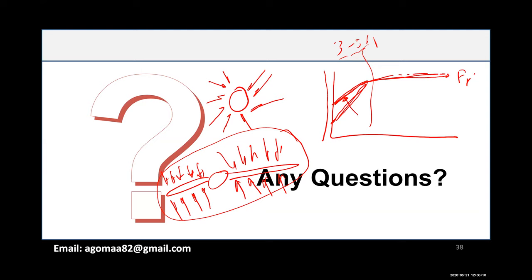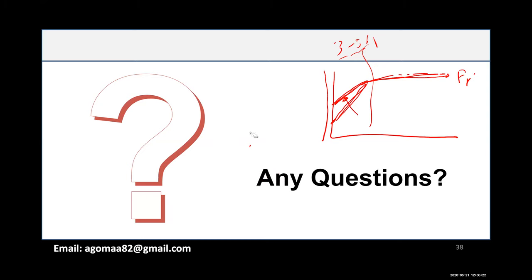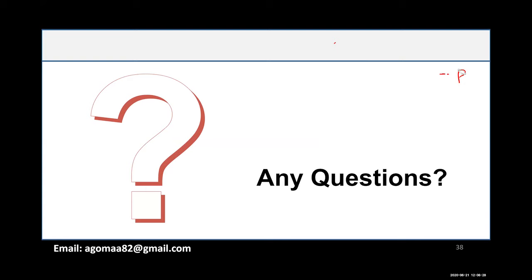Okay, so the next question, you mentioned something about a rapid decline of production as an identification of formation damage. And someone asking, is it the same for all formation types? I mean, the decline behavior, is it the same for all formation types? Rapid decline is happening when you are plugging either perforation or plugging the tubing, and that can happen for all types of formation, yes.